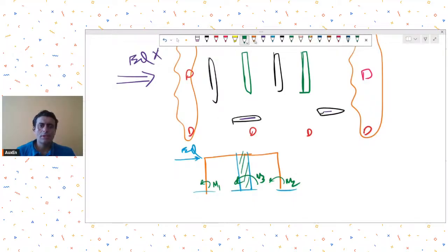So one way to resist earthquake forces is this, but there is also this other way, by the creation of axial tension compression couples. So through creation of axial tension compression couples, these EQ forces are resisted. So let's say this column will generate, and don't worry about the direction of arrows right now. I'm just making arrows so that the direction is reactive in nature.